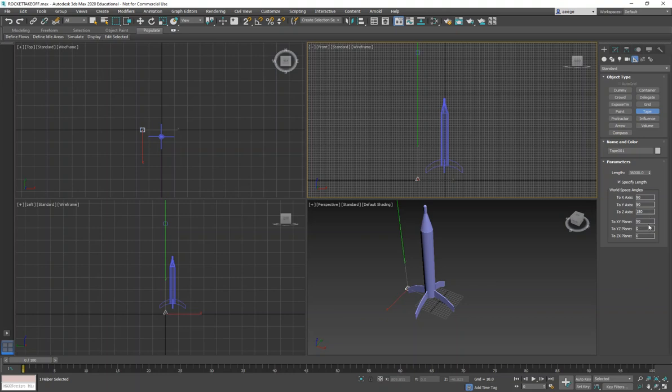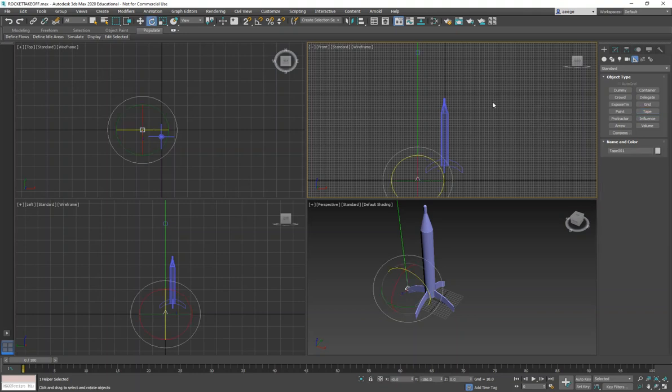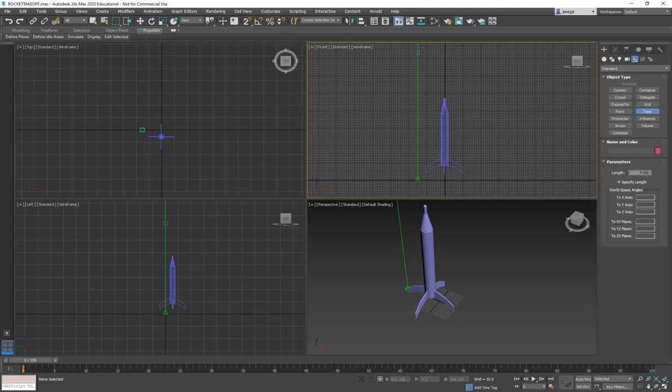And on the XY plane, this line is the specified length of the measuring tape, with 36,000 meters indicated. So hit the escape key, and click outside, in the air. Now we need another tape. This time we need 100,000. So you click on the Tape button and change the number to 100,000.